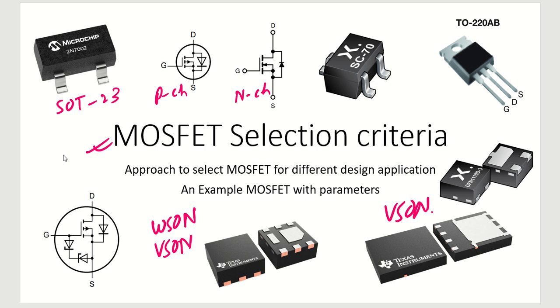You must understand a MOSFET should be such a suitable component that it does not go into an obsolete phase or something like that, right? As you can see, based on the package, we have various packages like the SOT23 package and the SC70 package. For low power applications, these are the most popular packages. Even we have a VSON package or WSON package for very small size, but these are SMD packages. However, they have better thermal capabilities and everything.